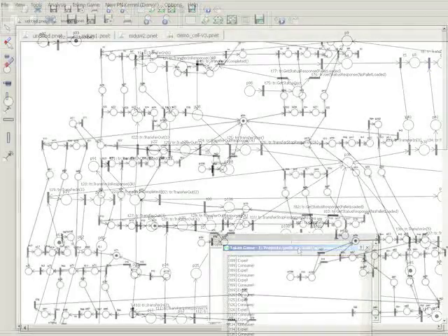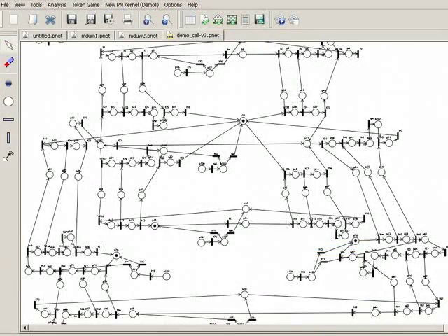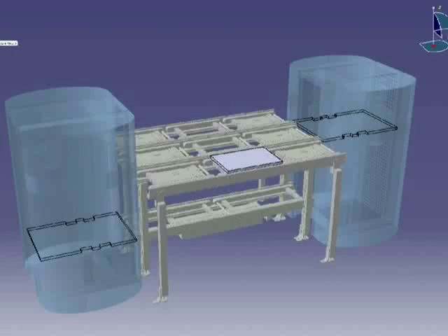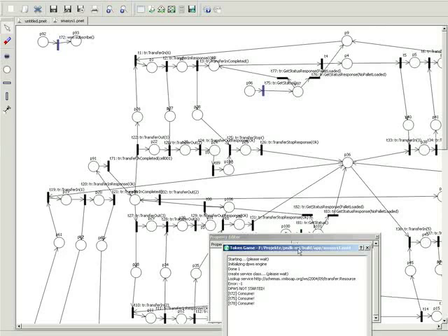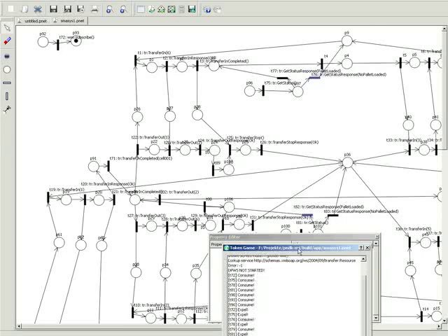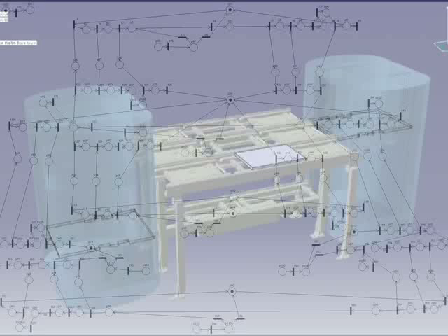Here shown is a view of the orchestration engine using the PNDK tool, which means PetriNet Design Kit, developed at Schneider. This tool is used here for designing workflows and as a runtime platform for the PetriNet models. As the simulation starts, the devices publish their web service interfaces automatically to the network. The orchestrator can then search the network for the required devices, connect to them, read their current status, and finally process the workflow. At each change of state, it evolves the system by following the sequence described in the PetriNet, which involves calling, waiting for, or responding to the services.